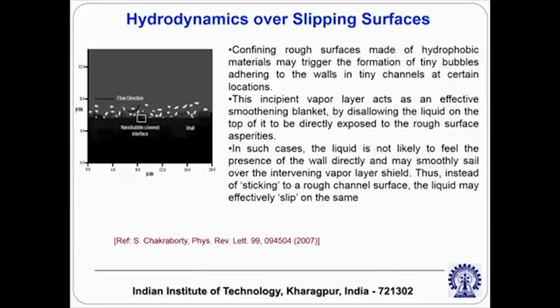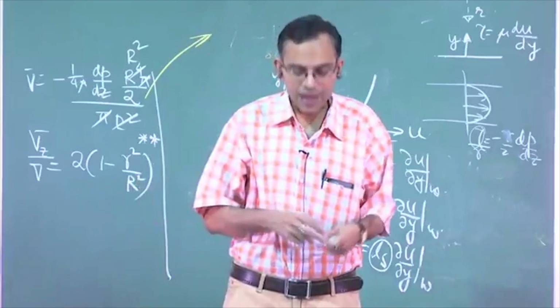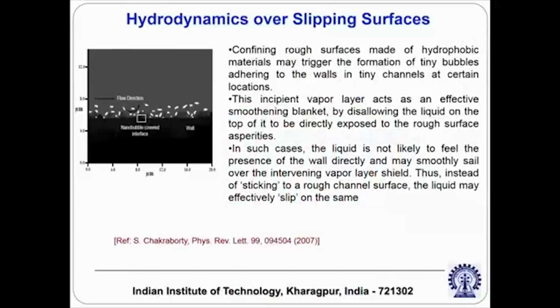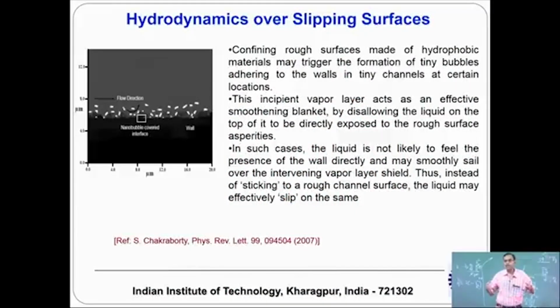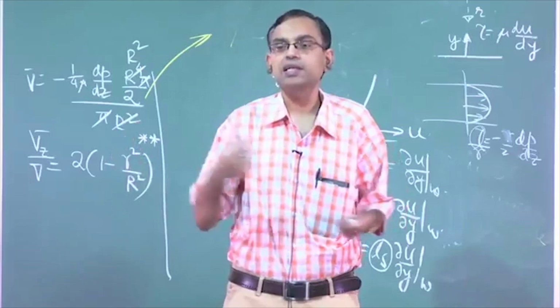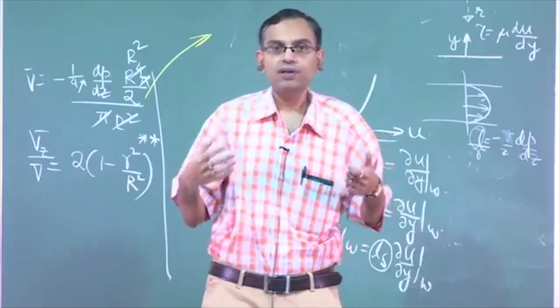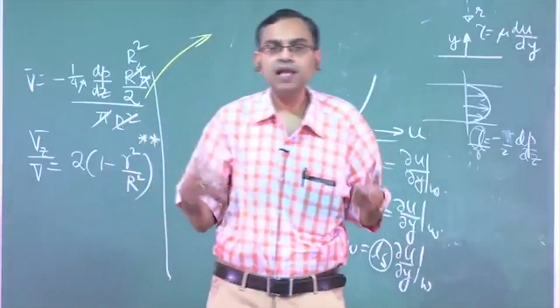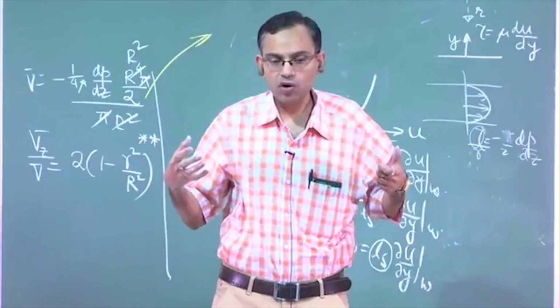It is important, because if you try to understand how you can control the slipping of fluid over a very rough surface, a rough and hydrophobic surface can promote slip in a confinement, research has shown this, then it may be possible that, overcoming the huge resistance that you can otherwise get in a pressure driven flow, you can pump fluid at an unprecedented rate.